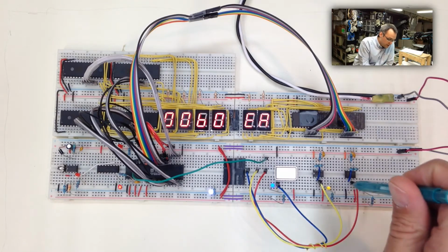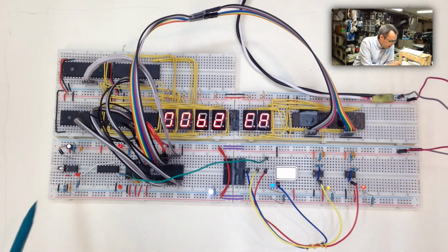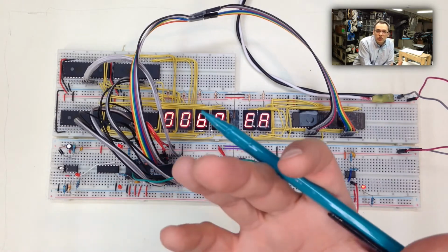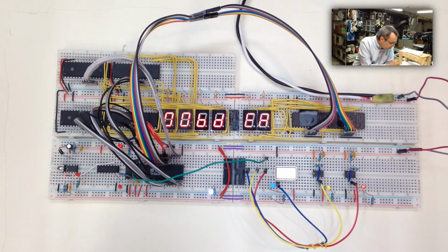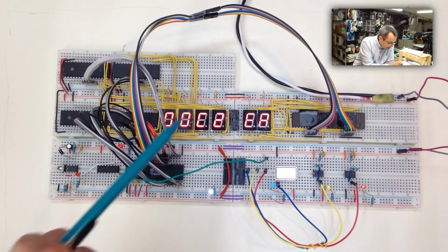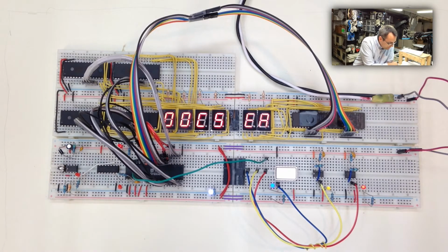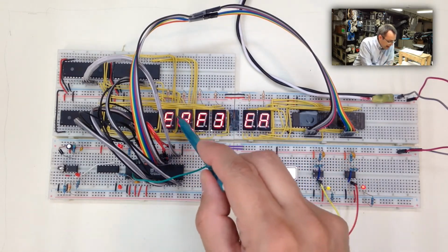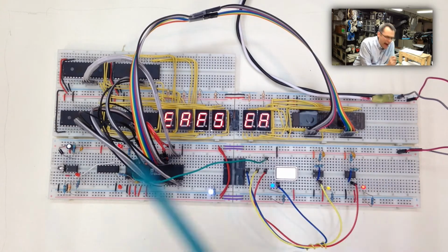But basically what that means is this started cycling the processor before the reset signal could take hold, before the CPU could recognize that there was a reset signal there and do something about it. So if we actually press and hold this, you'll get to see that half-second pulse. You'll see the light turn on, and we should see the CPU reset itself. There it goes. So the reset vectors are at FFFC and FFFD. And you can see that it fetched the address EAEA, which is the same as that.